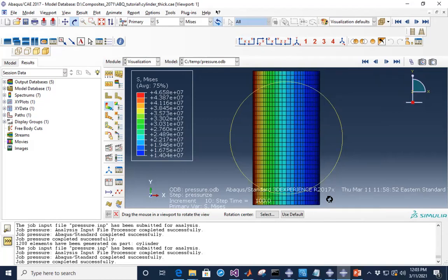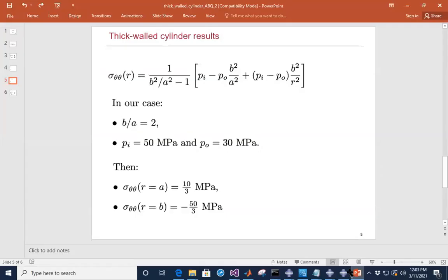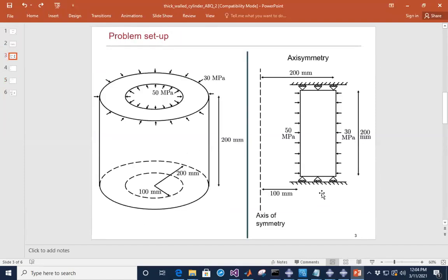So now what we had done so far is all on the plane strain cylinder, right? So we were looking at this problem where we had a vertical constraint on the bottom as well as the top edge. But now let's look at the other case with an unrestrained cylinder. This is the case that these are the set of boundary conditions you would expect, like when you try to use a piston cylinder assembly. This is an unrestrained cylinder case where there are no longer any displacement restrictions on the top and the bottom edge in the vertical direction.